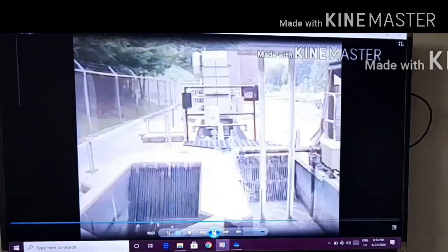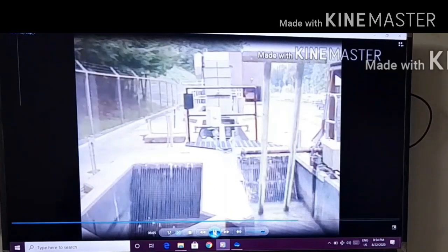A trash rack is used for removing large debris such as bottles and cans. It is generally a set of parallel bars placed at an angle or vertical in a channel. The bars are usually spaced 3 to 4 inches apart, and may be either manually or mechanically cleaned. Regular removal of debris from the trash rack is necessary to prevent problems with rodents and odors. The bar screen operates in a similar fashion to the trash rack.